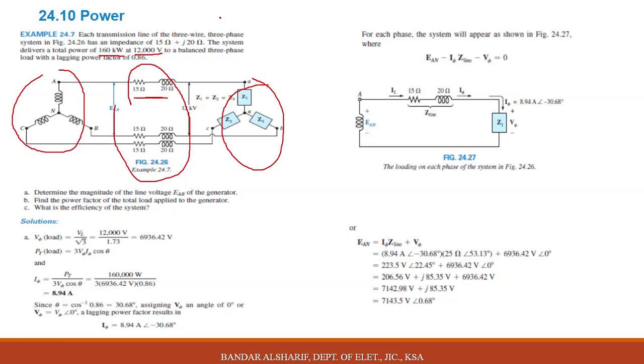In general, in all electrical books, if a voltage is mentioned in a three-phase system connection, for example motor, generator, transmission line, and it does not specify which type, you will consider it as line voltage. Please be careful about this information. You will get a benefit from this information later. In other courses, any voltage not specified, you will consider it as line voltage. Okay, let us start.